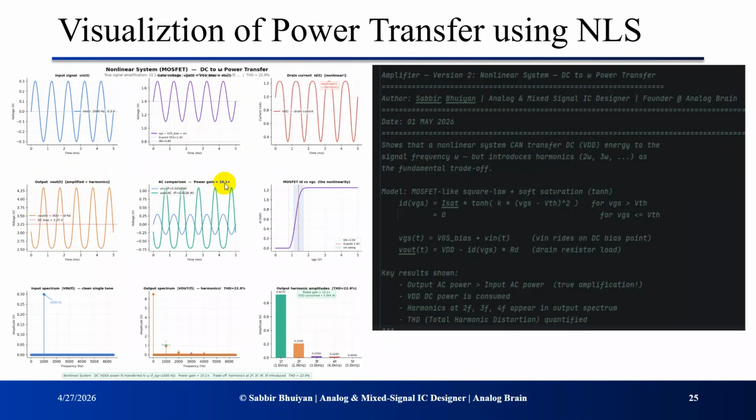Okay, so AC comparison, the power gain is 10x, and we can see here the input is 1000 hertz. Okay, the amplitude is 0.3, here 0.3, input 1000 hertz, output spectrum 1000 hertz. Okay, and it is not now 0.3. It increased in 1f, we see it's 0.9272. So the power gain is 10.1 times, but the trade-off here is the 2f, 3f, 4f, and 5f.